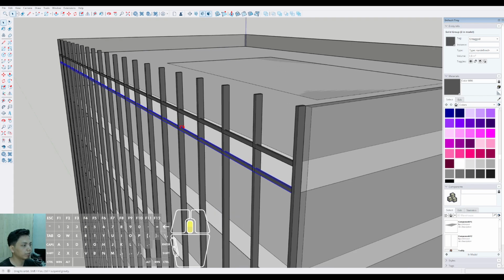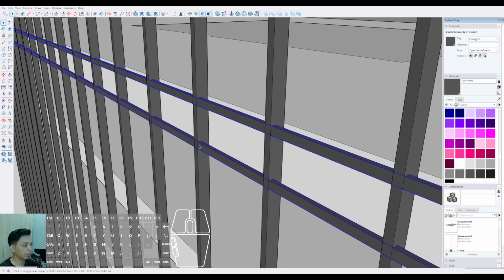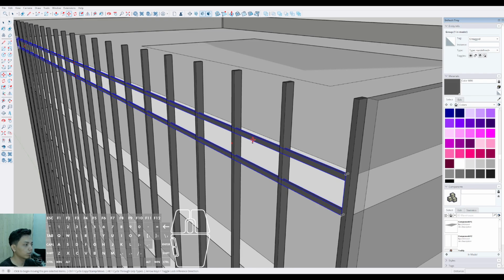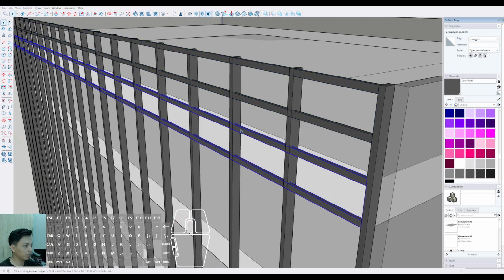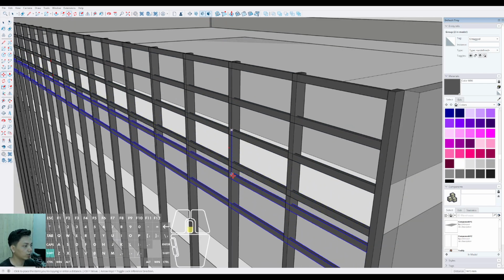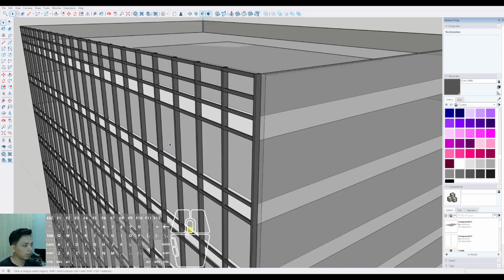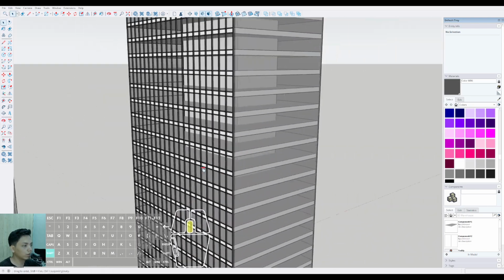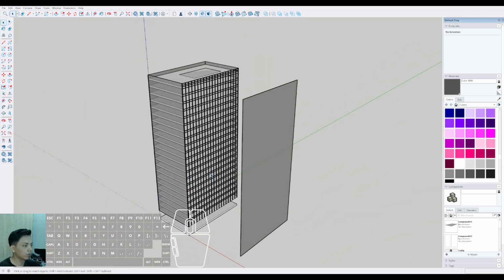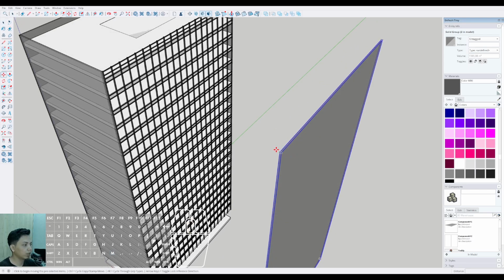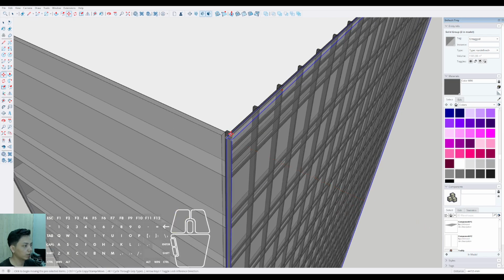Okay, then you can try to make group this one, make group, and then you can select a move and duplicate it approximately in this position, and then you can duplicate it again for each floor over there, and then we can type x20, enter. So it will be arranged automatically by the floor composition, and then you can select move, and then you can place on this position.